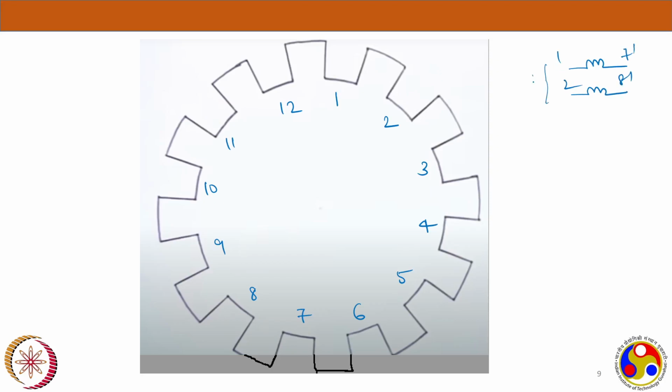These are coming under the south pole, we assumed, and the next ones are 7 to 1 dash and 8 to 2 dash. Then they definitely will come under the north pole. So we will see that connection here itself now. See, now the start of each coil we know the numbers, and all the 4 R phase coils we know. So let's place it here.